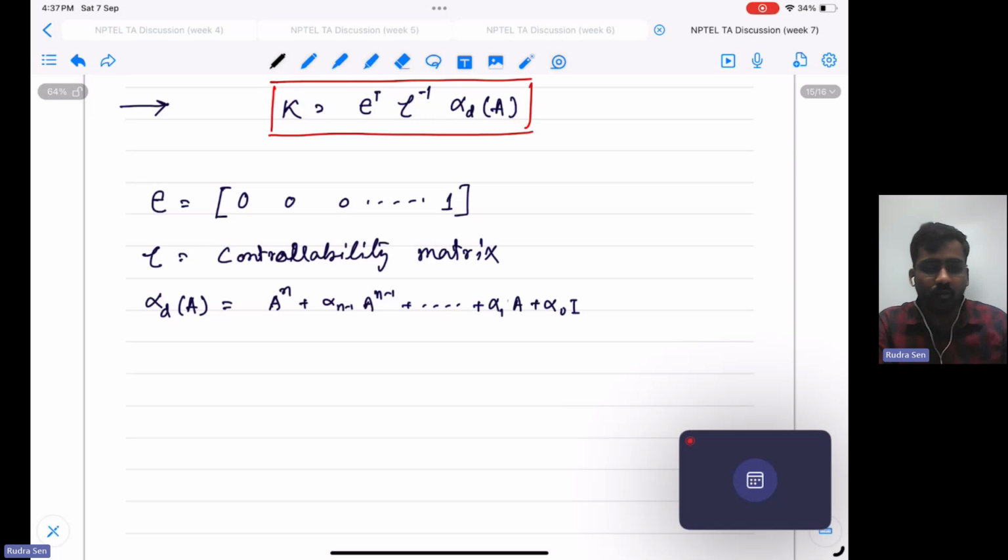So all these formulas are applicable for the pole placement scenario. We have already been given the desired pole location; our closed loop system should act like the desired characteristics. If the poles move to the left hand side, the left half of the complex plane is the stable one, so we always want our system poles to lie on the left half of the complex plane.